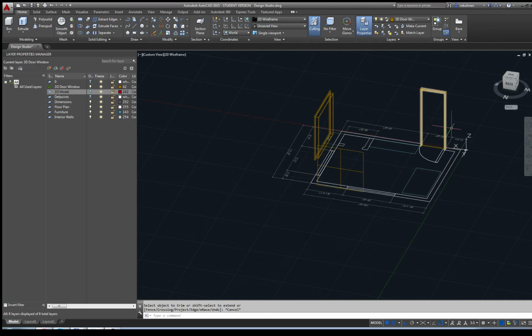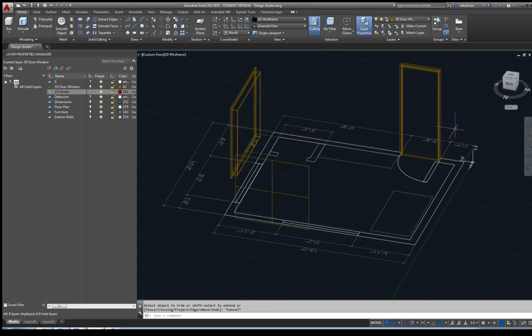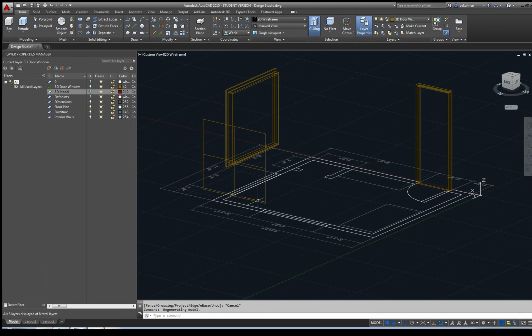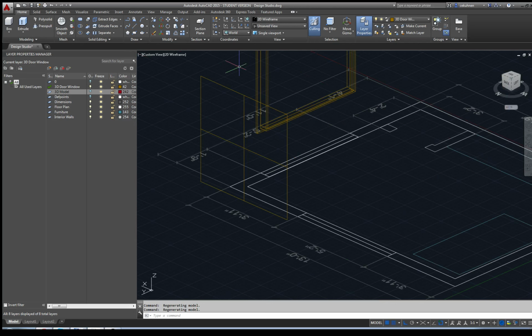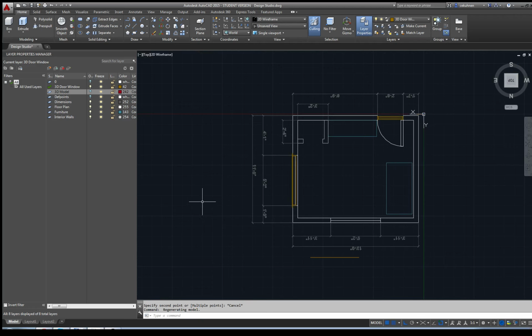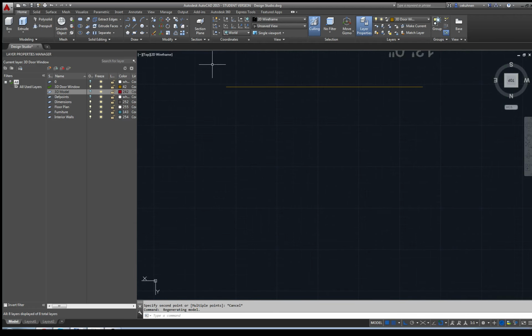Oh, it doesn't work. Okay, I don't necessarily know right now what the problem is, but I assume what I did wrong is maybe those lines don't perfectly match up. But this is actually a good situation to show you how we work around it, because knowing the software very often is also about knowing how to do things the other way. So I have a 4 feet 9 inch tall and 5 feet wide window. And I know if I start cleanly drawing everything in orthographic, it will work.